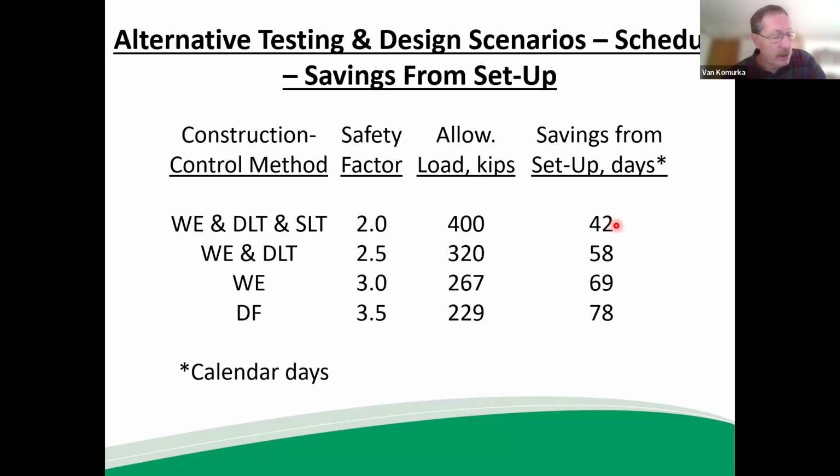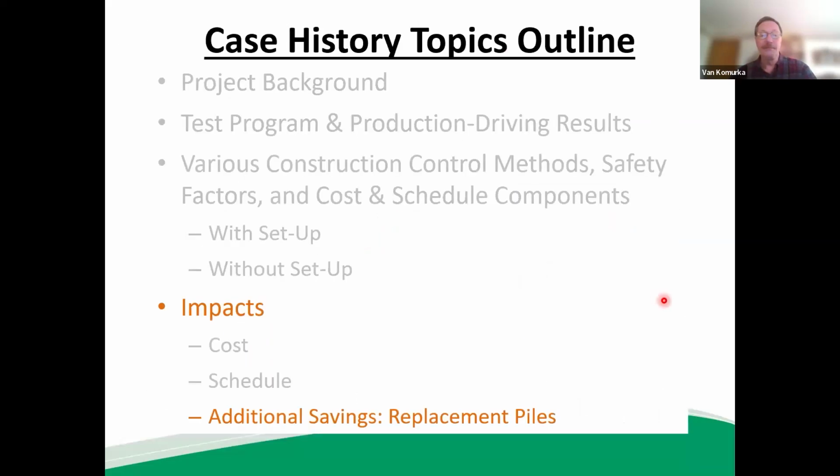Now, if you recall, the restrikes were performed anywhere from 36 to 54 days after driving. So incorporating setup virtually saved enough driving schedule, in terms of driving days, to pay for the testing; the production driving schedule saved as many days as the testing took. So again, when somebody says we don't have time for testing, you need to look closely at that and say, well, testing may save you time.